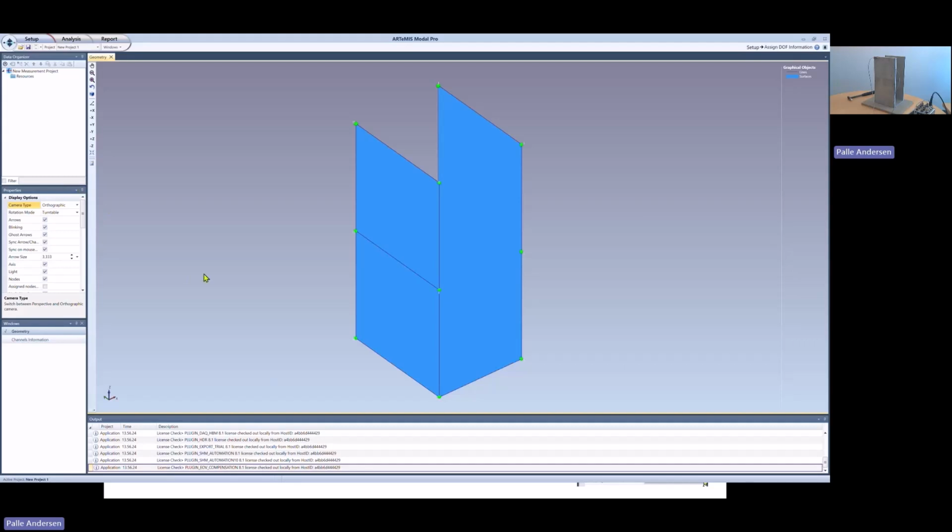And this allows me now to graphically define where the different response and impact positions should be. Maybe you can see on the camera that there are 2 sensors located in the corner, 2 accelerometers. So this will be our place of response measurements. I can try now to go here to insert object and define one.